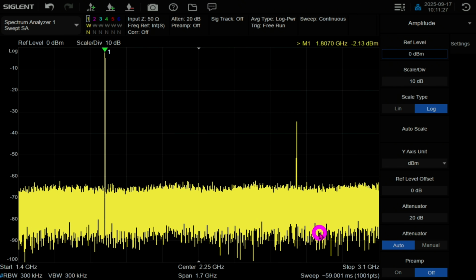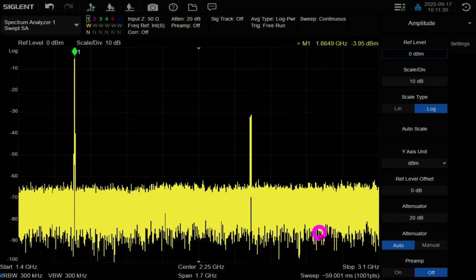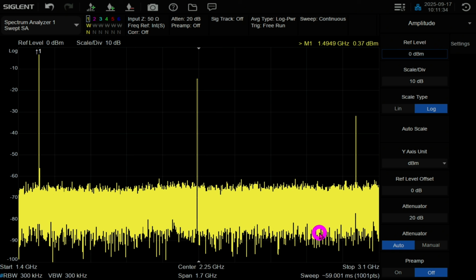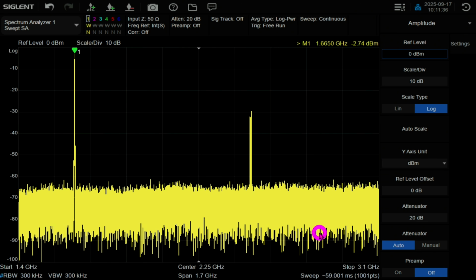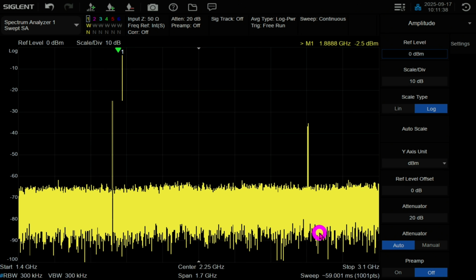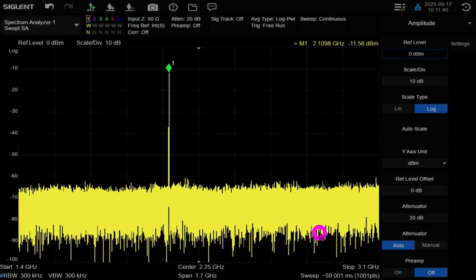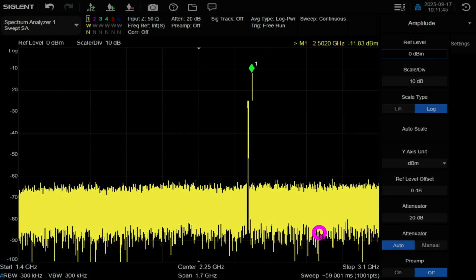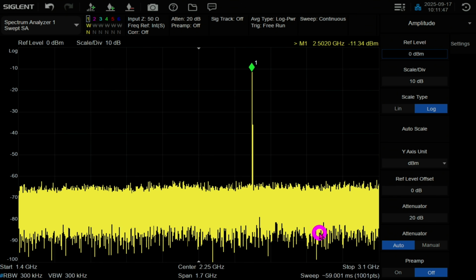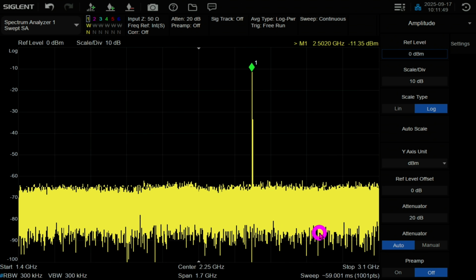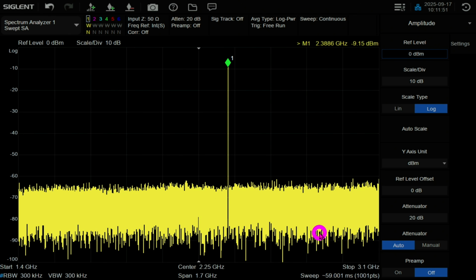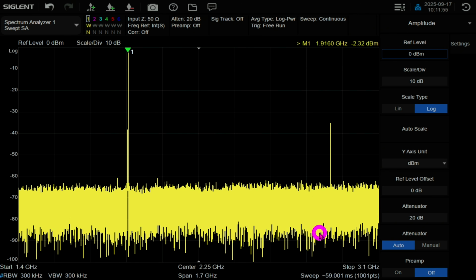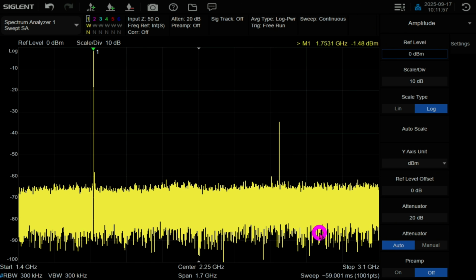And look at that. Yep, the VCO has no problem. It should go all the way to 1.5, and it does. Yeah, even goes below that. So yeah, the VCO range really does cover everything. That's not the problem. Oh, that's a shame. So the VCO works perfectly fine. And it anyway locks here perfectly fine. All right, well, that was a good thing to try, but this tells us that the VCO is okay. It definitely goes as low as that. So it doesn't unlock because the VCO can't cover this frequency. There must be another reason.